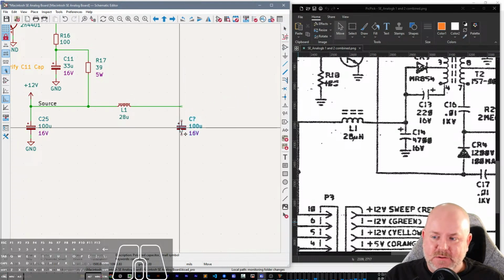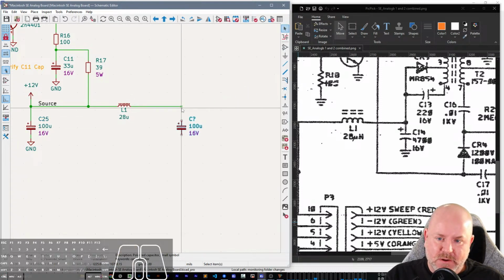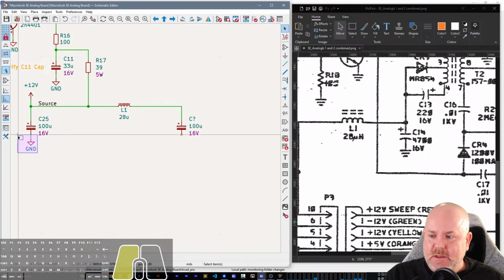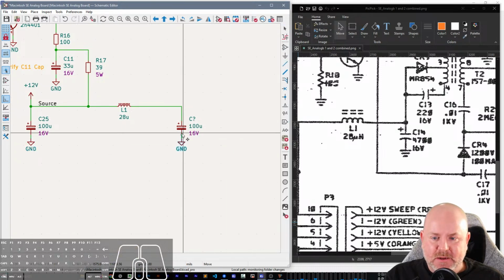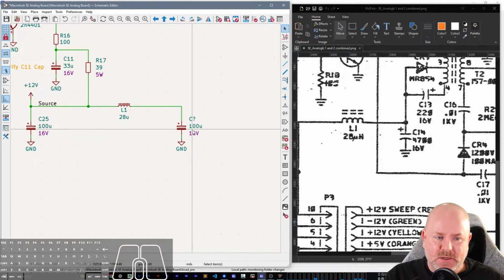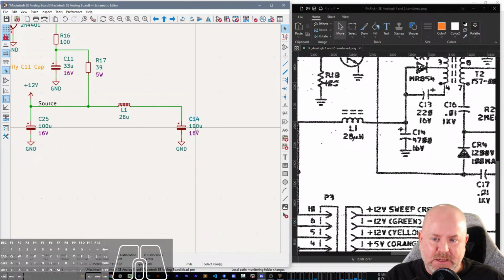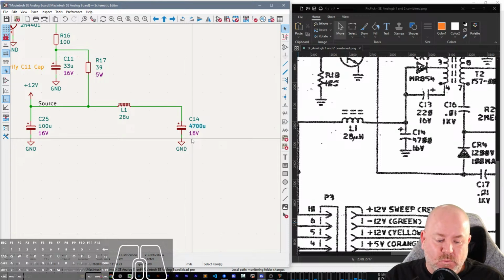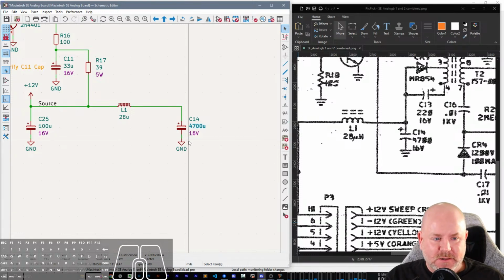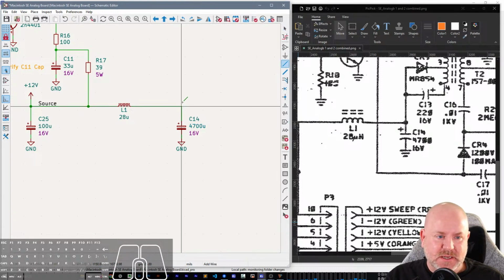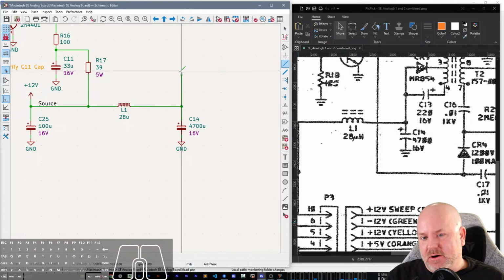On the other hand, the benefit of having a standardized pinout is it would make designing in different types of op amps really easy, right? That would be a really big benefit. These 3 op amps will work fine, or somebody comes out with a new version of an op amp that has lower noise or better offset or something, and it's like, hey, I can just drop this in, it'll work fine. But I would argue the same thing with, never mind.